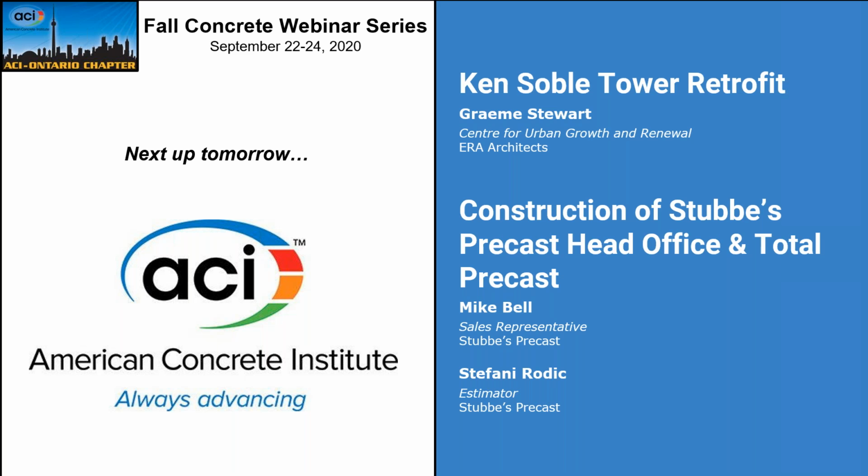One of the things Nick talked about was the testing. Absolutely. I had people that were using neoprene caps on the cylinders and figuring out they could measure the MOE. And of course, now we've got 2 different materials that we're measuring. And they weren't preparing them properly, as Nick was saying, so we got them to get a grinder, so the surface was plain and consistent.